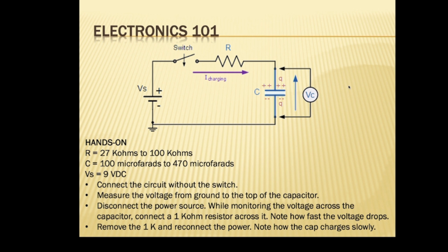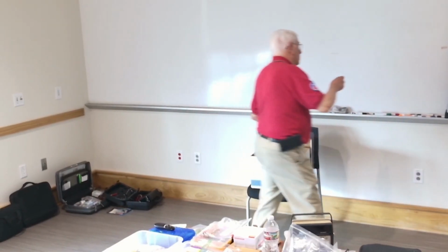Now then, get your pencil out or your calculator or whatever you like to use. Get the value of your resistor, the value of your capacitor, and see what kind of time it should take to charge that capacitor, doing the RC time constant. What did you say my resistor was? 470K. Those resistors that I handed out were 470K.